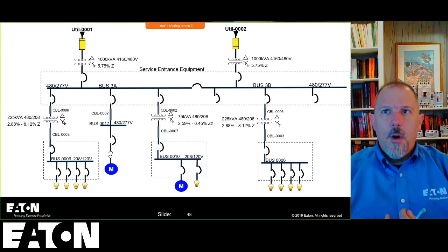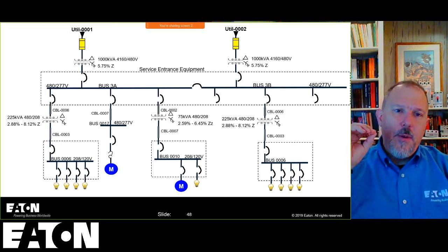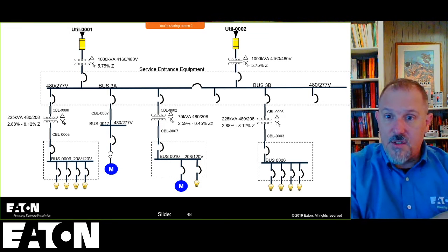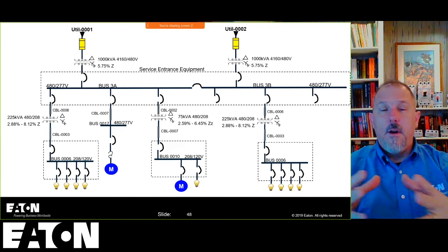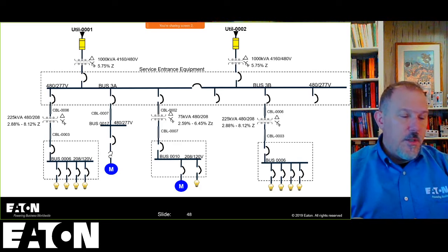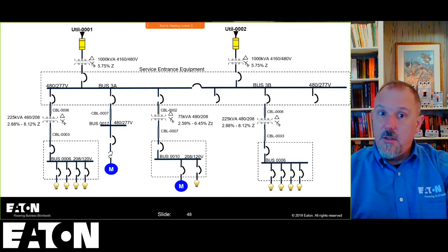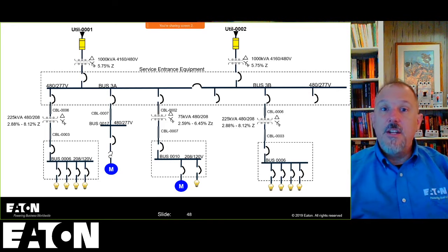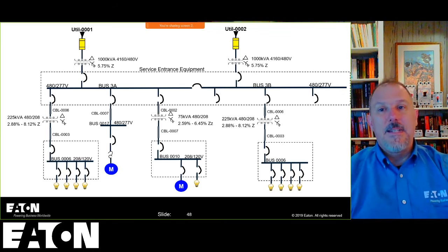So you want to make sure that anytime you change your power distribution system, anytime you add motors and subtract motors, you have to understand, go back to my fault current class from a few weeks ago. What impacts fault current? You add motors to a system, that'll increase fault current. That could increase or it could decrease incident energy. Subtract motors from your system, that will decrease available fault currents in some parts of your distribution system, and that could increase incident energy.